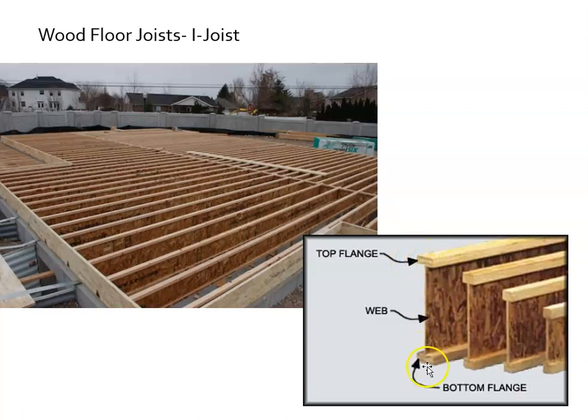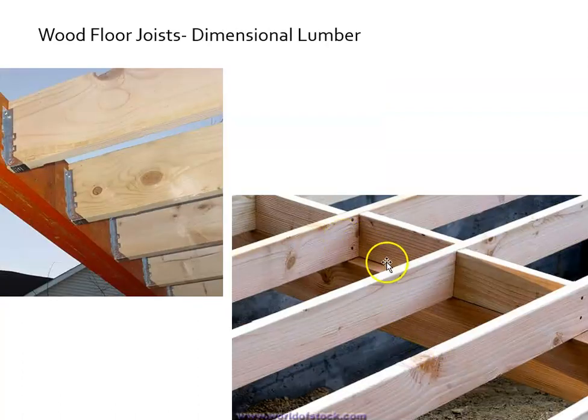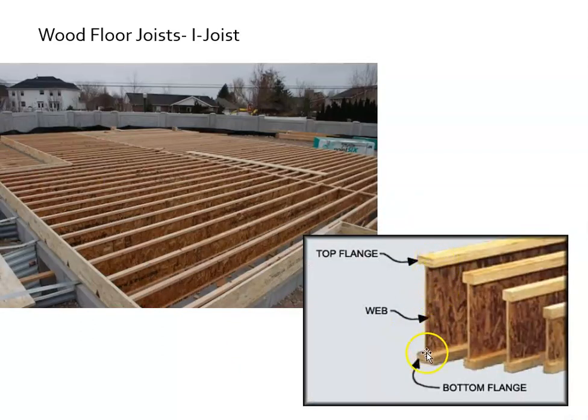It's structurally designed, provided with only the wood that it needs to do the job that it has to structurally. And just like steel I-beams, they cut out all that additional steel that they don't need. There's a lot of wood that's not needed. So in a wood joist, there's a lot of extra wood here in the middle of the body that's really not needed structurally. So this is very efficient, and they're very light as well. Probably one carpenter could carry this entire joist. Could be a little unwieldy maybe, but they're surprisingly light.